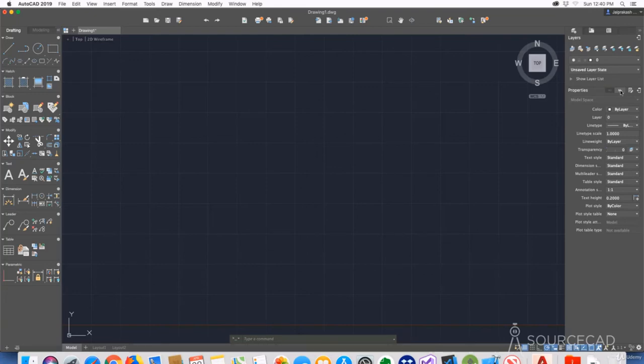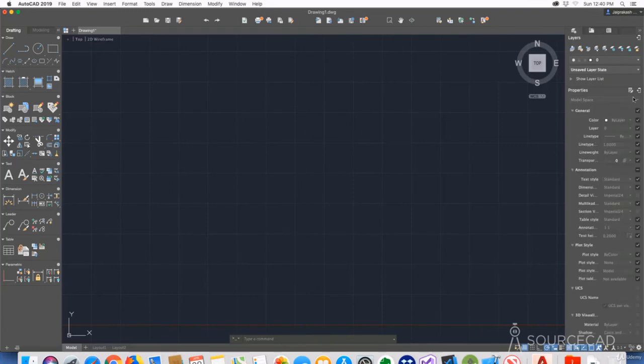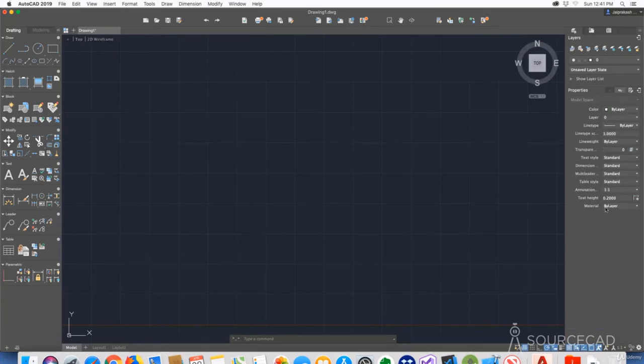Now this list is fully customizable. It's your list. You can just modify it, and you can add or remove properties in this list. Now to modify this list, go to this edit option and check the properties that you want to keep and uncheck those which you don't want to keep. So for example, in this case, we don't want to keep any properties related to plot style. So here I'll simply uncheck this first option here on the plot style, and all the plot style properties will be unchecked. Also, let's say that in 3D visualization, we do want to keep the materials. So I'll only check this material, and now we'll have the material option. So once you're done with this, click on this edit icon again, and we are back to this, and here we have the material property. So again, I'll move back to all properties.